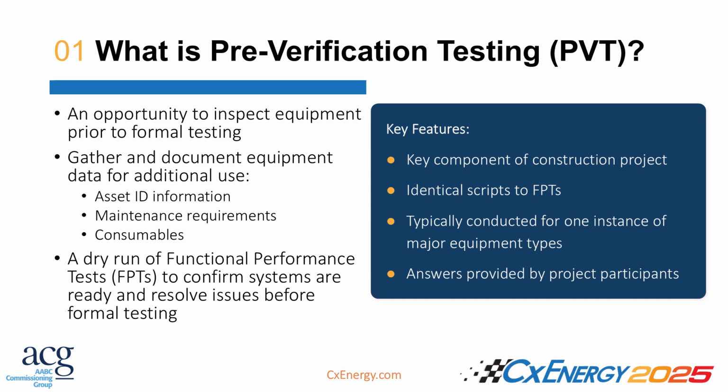So what happens is the systems go through the installation process, through static testing. The teams will be completing their checklists, the energization checklists, startup checklists, pre-functional checklists. And then a time comes when the teams are getting ready for the functional testing.